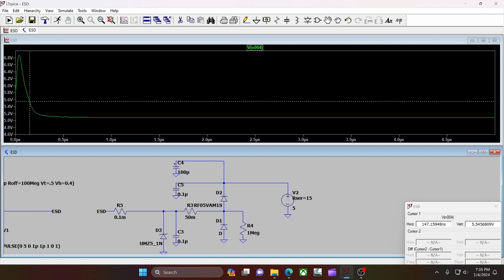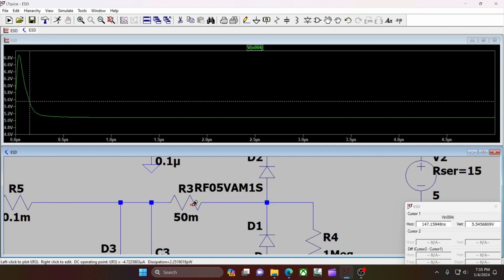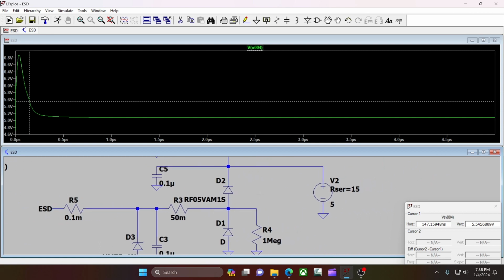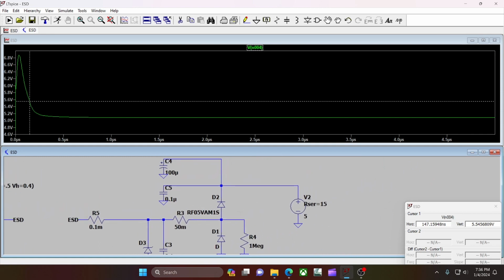You may have power plane, ground plane, maybe capacitance. Or if you don't have a power plane, you'll have a ground plane that's close to your signals. That helps. That is not in here. Also, good and bad layout practices. We didn't look at what happens if this is further away. That goes for them both. I mean, this right here, this 50 milliohm, kind of simulates trace impedance. But does it really? Because we're at 100 and 500 megahertz.